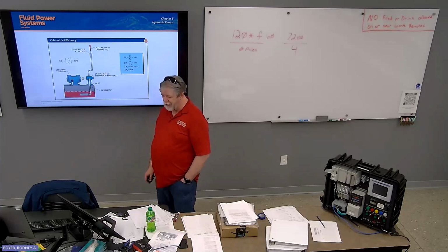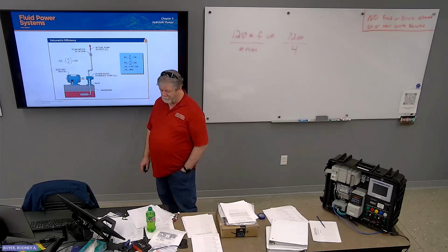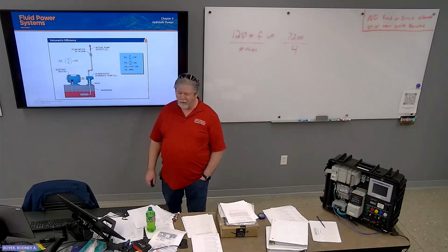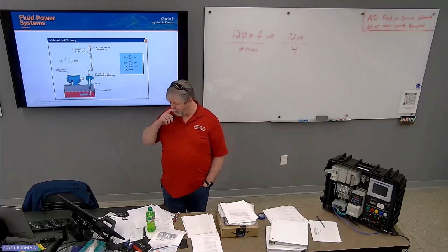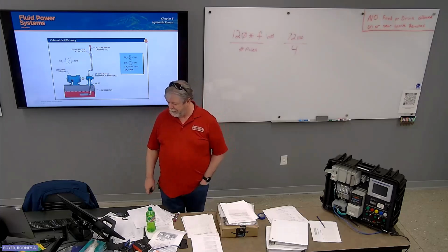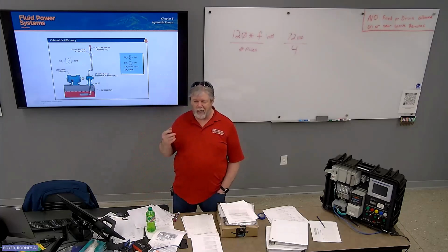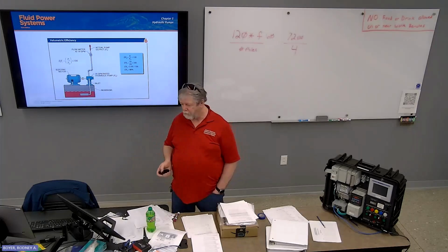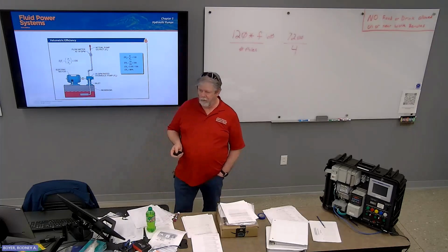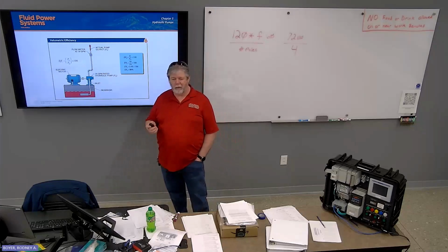Volumetric efficiency is what the pump is capable of versus what the actual flow through the system is going to be. Every time you turn a corner or pass through a device, you have a little bit of pressure drop. You'll also typically see a reduction in flow.